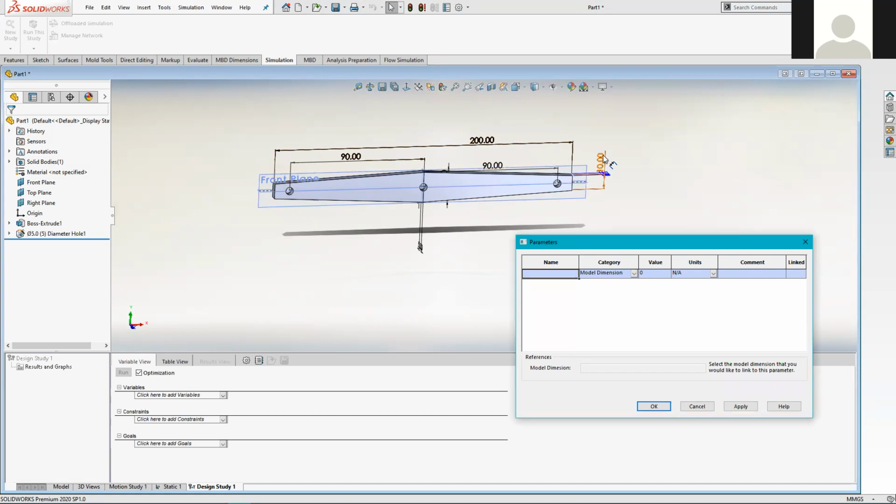And we're going to just click on one of them. So we'll click on that 10. It collects the value into there, so it's collected the 10. We have to then name it. So we're going to call it end thickness, like that. Press enter, and then you'll be given the next row in the table.